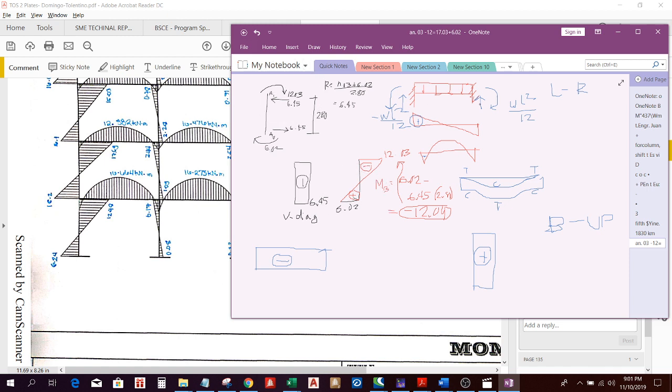Going down, so this is analogous to, or corresponds to, the right portion of your beam. This is the right portion of your beam. Going down, negative area. Going down, negative area. So I think you should follow that procedure or sign convention in drawing the correct shear and moment diagram. So in order to be consistent,